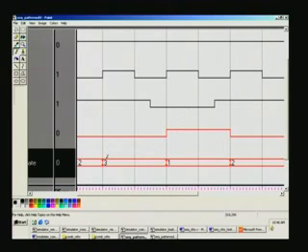No. So I explained earlier. So state changes at this point of time, but this output is dependent upon this state. So it has just changed here. It has not yet got stabilized. It gets stabilized only at this point of time. So only that, because this is basically a state machine. It functions from clock to clock, not in between. So what you have changed here, you have to wait for the next clock to arrive. Then only this corresponding state will be actually processed.